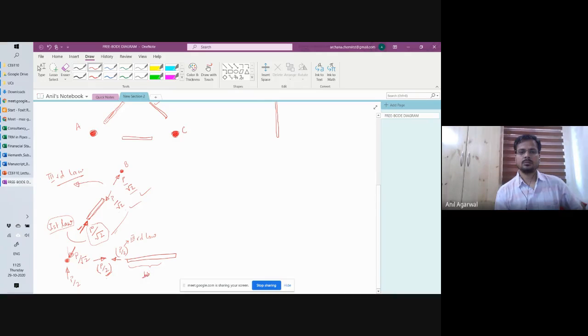Again, we will apply first law, which will give us a balancing force on the other side. It is coming from first law. Okay. Again, the node comes. Now for this node, we get a force of P by 2 here. And you can split a structure into as many parts as you want until you are confident that you have taken into account all possible reactions and all possible combinations of Newton's third law, action and reactions. Okay, there is no upper limit to how many times you need to divide it.